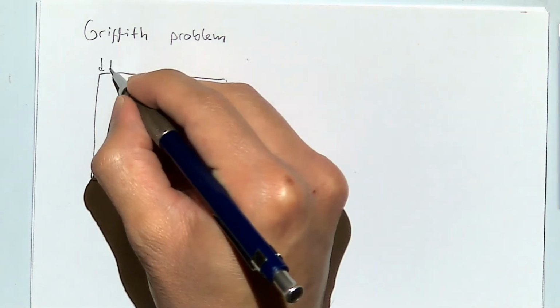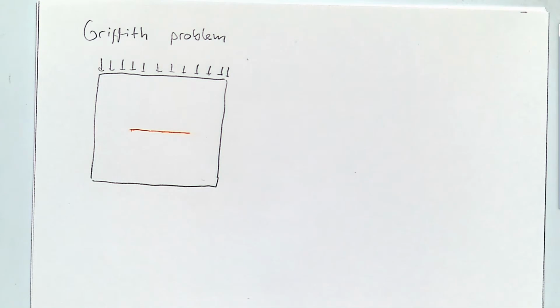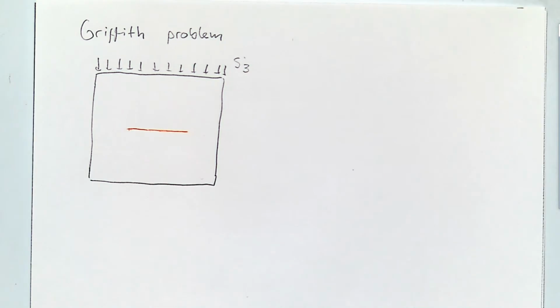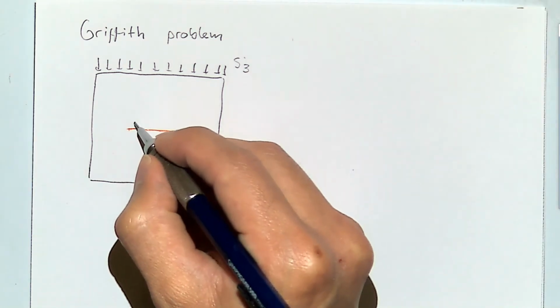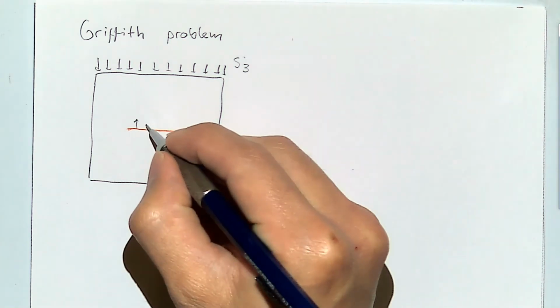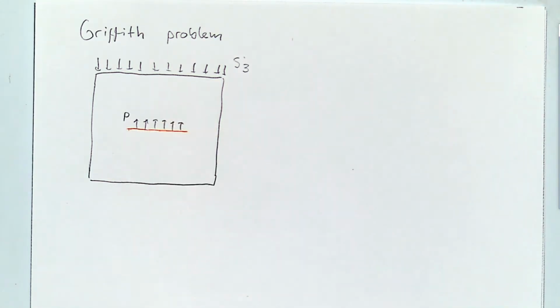and outside, perpendicular to this fracture, we're going to have a minimum total stress, and inside the fracture is just a line right now with zero thickness. So I'm just drawing the pressure that will be inside the fracture. This one will have, let's just call it for now, just a pressure P. This fracture, in order to open, has to have a pressure which is larger than the far field total stress.